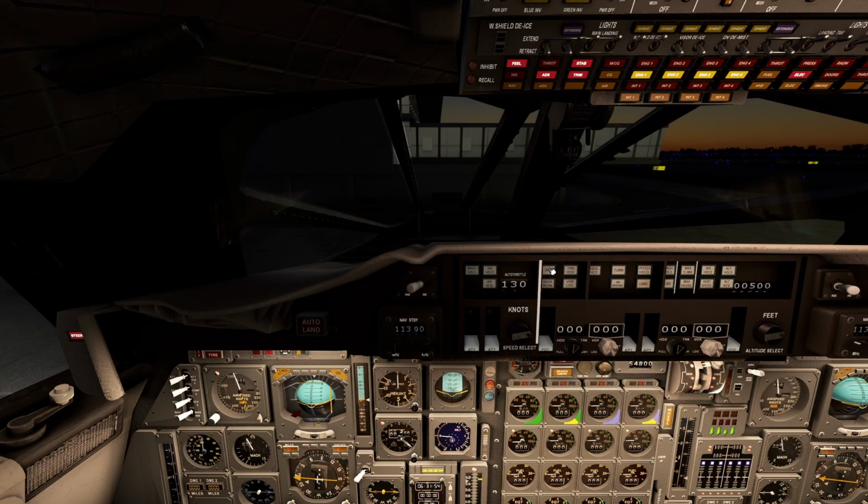What we're going to use is INS, which is going to follow our very simple flight plan of Microsoft Flight Simulator. That is easy. GPS is working fine. The problem with the autopilot is that all the altitude modes are not really working. So especially max cruise, which usually climbs the plane very, very slowly to keep a certain max speed, is not working. It's much too clumsy. You're going to end up in a frequency up and down, and you're going to lose stability. So everything we're going to use of the autopilot is actually alt-acquire.